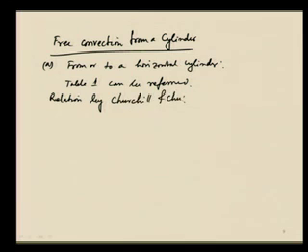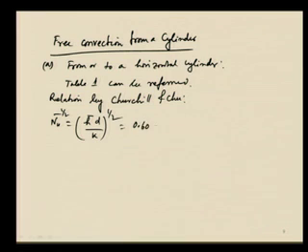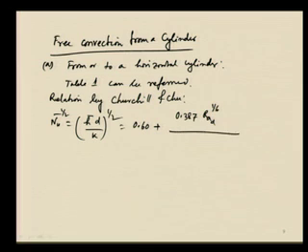The relation says that Nu bar, which is h bar d by k, where d is the outside diameter of the tube we are interested to study, is equal to 0.60 plus 0.387 Rayleigh based on diameter of the tube, to the power 1 by 6, divided by, we have 1 plus 0.559 by Prandtl, whole to the power 9 by 16.